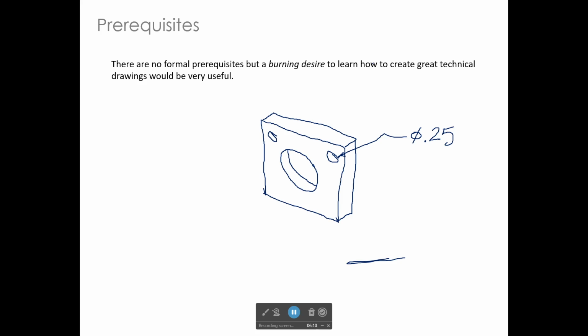Now, what you would do next, probably, if you decided that you were going to actually build this part, is you would draw just the front view of that object. Just like if you were looking straight on in this direction right here, and draw what you would see. So if I sketch that hole, and then I sketch those two small holes up here in the corner, of course they would be round, this would represent the front view. And this is also a technical drawing.